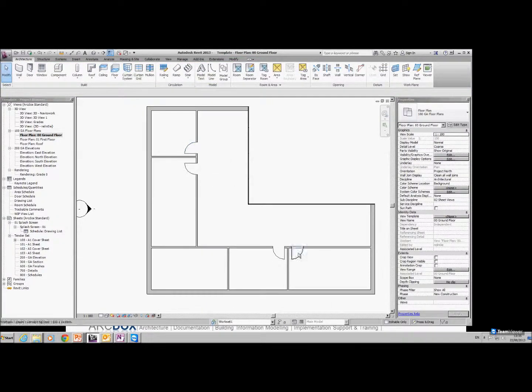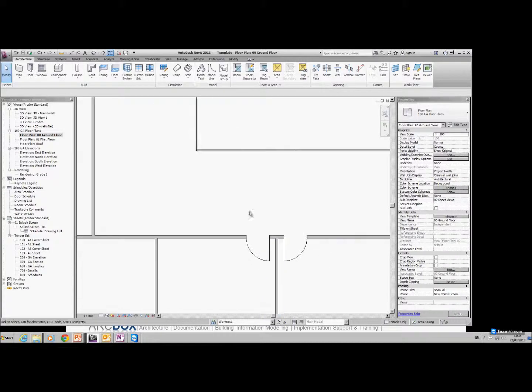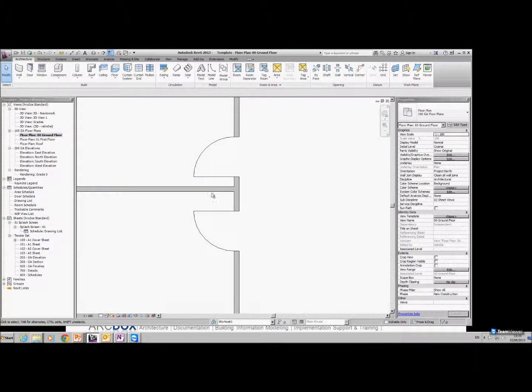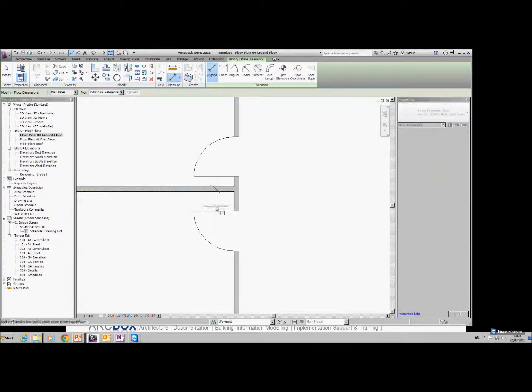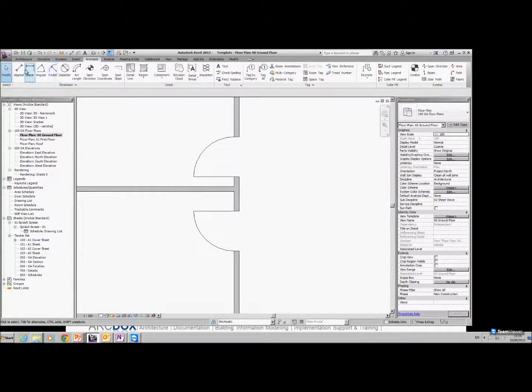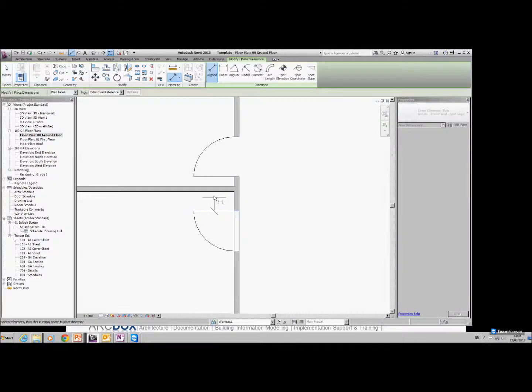And they're off. These don't look actually equal. I'll go up here. I want these the same distance. So I'm going to annotate a line from the center of that to the edge of here. Actually, I have to do it all in one go, to here, to there, and then click equals, and that makes them equal.